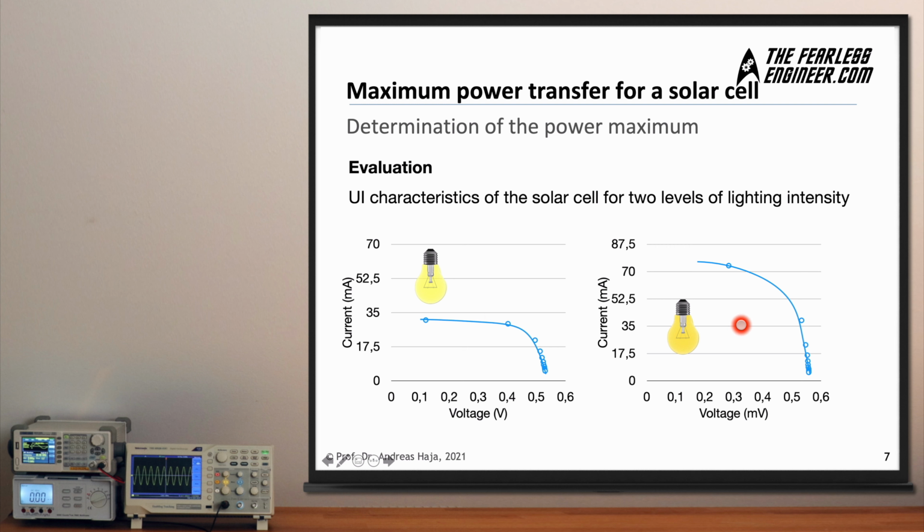On the right side, for the high powers, for the high intensity light setting, the curve looks a little bit different. There's not so much this constant part, but we have this slight decrease in the beginning, somewhere between 0.2 volts and 0.4 volts. Then it gets quicker, and towards the end we have the majority of the points being in close proximity to each other. And just as before, an increase in voltage corresponds to a drop in the current flow.